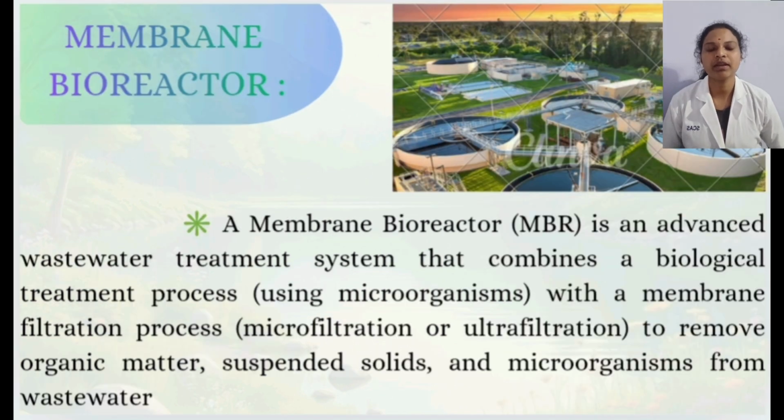What is meant by membrane bioreactor? Membrane bioreactor is an advanced treatment system. It is used for wastewater treatment. It is a biological and filtration system, where microorganisms and filters like macro and microfilters are used to remove the organic matters, suspended solids and some other waste from the water.